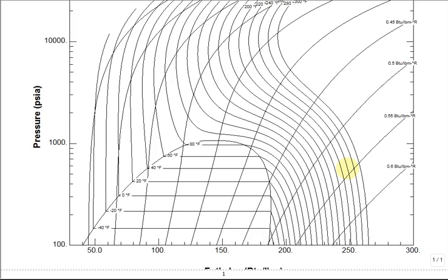And so we know that the one heat exchanger is going to be around 300 psia. That's going to be the low pressure. And let's say we come out of that at 0 degrees F and saturated vapor, kind of doing the traditional compression system. And let's throw it up there, go way up to, when do you want to stop compressing it? When the outlet is 300, when the outlet's 260, when the outlet's 220. Here's the outlet is 200 degrees, right? Isn't that the line of constant 200? Let me count. 200, 220, 240, 260, 280, 300. Right, that's a line of constant temperature of 200.